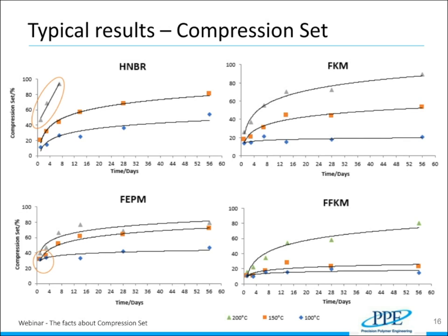Okay, so we've got time for just one or two more questions. Does pressure affect compression set, and if so, how? Compression set will be affected to an extent by pressure. The main thing that happens with pressure is that the stresses imparted will be higher, so there'll be an increased amount of set through that, and pressure can to an extent increase the rate of reactions by increasing concentrations inside the elastomers. I think the key thing that pressure does is that it is there to form seals and to be the force against which the seal reacts.